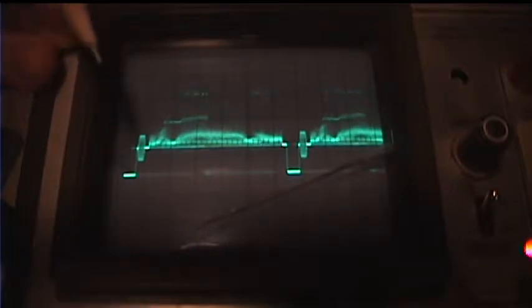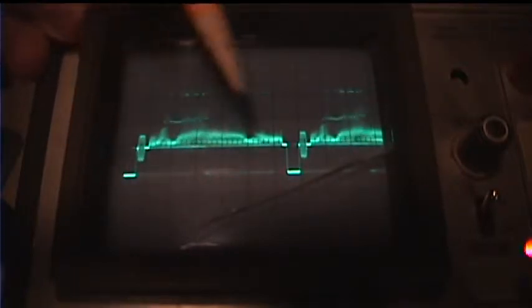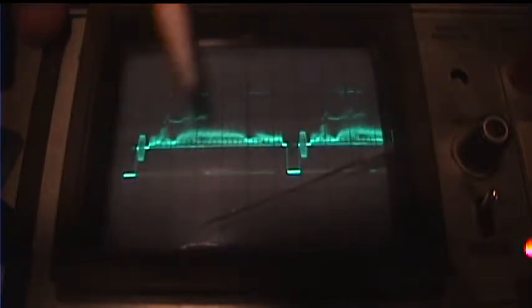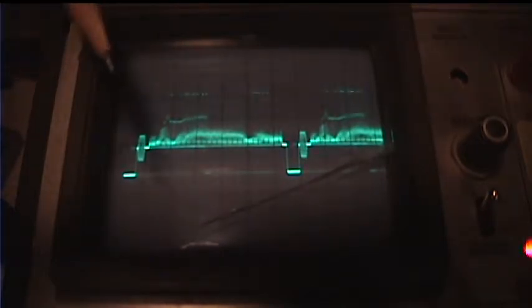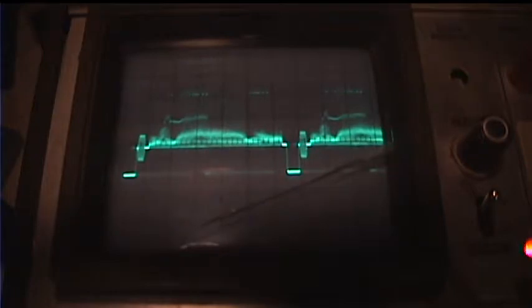Things you can notice are these downward going sync pulses. These denote the start of each scan line of video. So after the sync pulses, this part of the active video signal, the higher up the signal, the brighter the picture is.